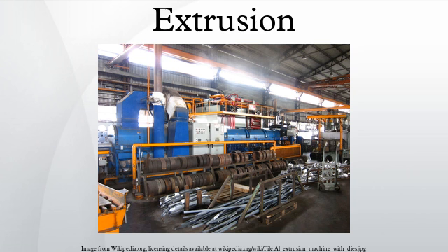Biomass briquettes. The extrusion production technology of fuel briquettes is the process of extrusion screw of wastes or finely shredded wood waste under high pressure when heated from 160 to 350 degrees Celsius. The resulting fuel briquettes do not include any binders but one natural, the lignin contained in the cells of plant wastes. The temperature during compression causes melting of the surface of briquettes, making it more solid, which is important for the transportation of briquettes.